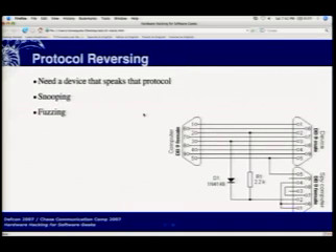If you have to reverse engineer a protocol, a communications protocol between two devices, you have a few options. You snoop on the protocol if you have something that can speak it, so you can just watch as the two things talk to each other. The schematic that's up here is a serial sniffer. I believe this is a half duplex one, so it will only catch one half of a communication. But this is for just ordinary RS-232 serial.